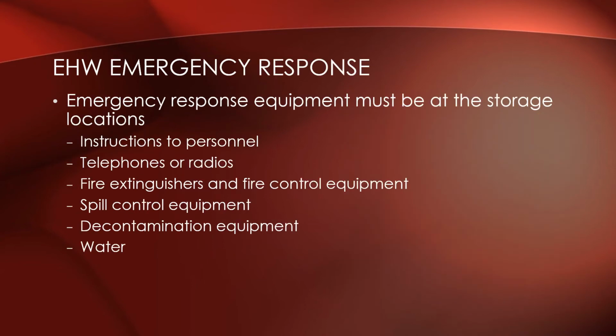In an emergency, there must be emergency response equipment available at the storage locations, as well as with hazardous material transport vehicles. This equipment includes instructions to personnel, telephones or two-way radios to contact first responders, fire extinguishers and fire control equipment, spill control equipment, decontamination equipment, and water.